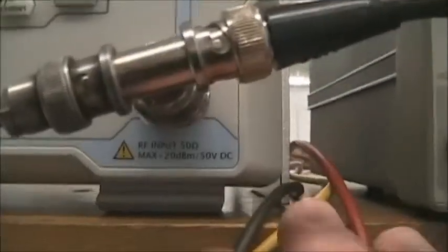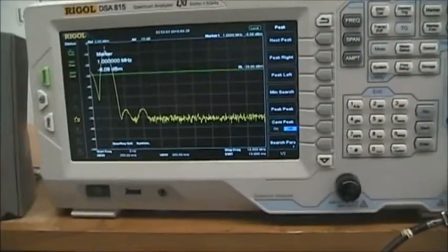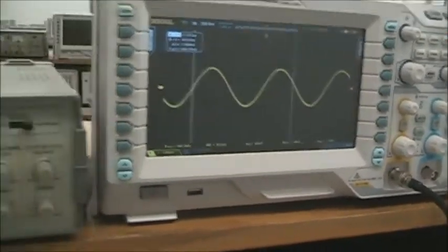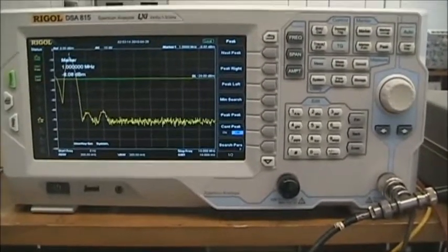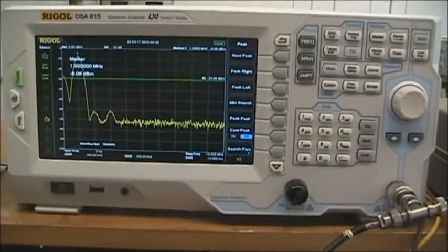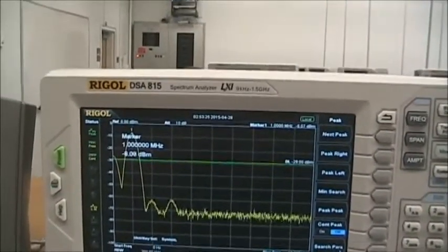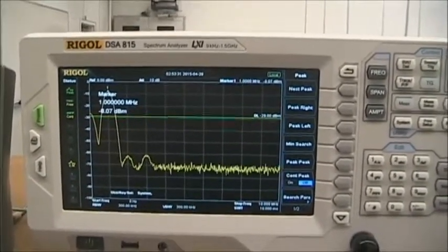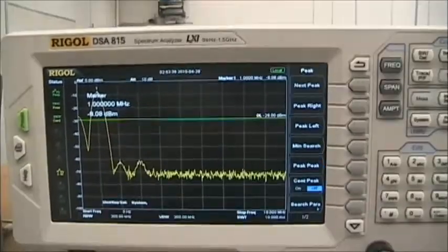The spectrum analyzer is a 50 ohm device. This means that its input impedance is 50 ohms, not 1 megohm like the typical scope. This causes the signal to reduce in value by 50%. If we recalculate based upon 250 millivolts as a peak-to-peak signal, we actually get minus 8.13 dBm, or a minus 6 dB reduction. So now this is why we have the minus 8.08 value for our signal.